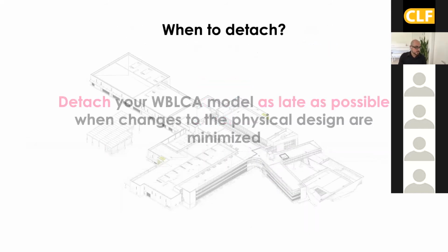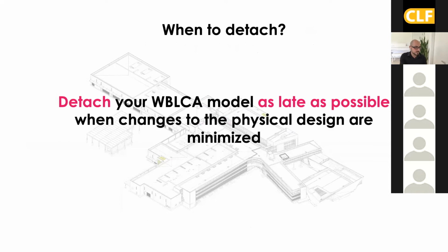And when to detach a model. This is a little bit of a tough question because, as I mentioned, you need to have your baseline model and your proposed model. The second you detach your model from the central, your changes are not reflected anymore. I really recommend, again, to do baseline or to do bay models and assembly models early on, but keep the model attached.